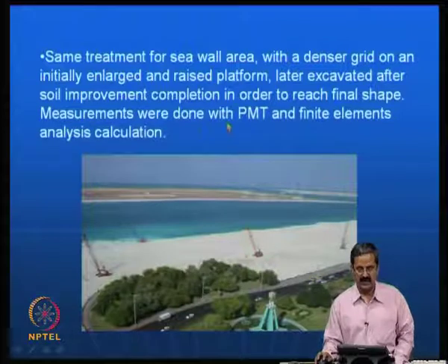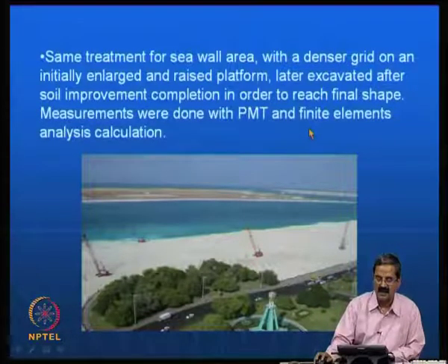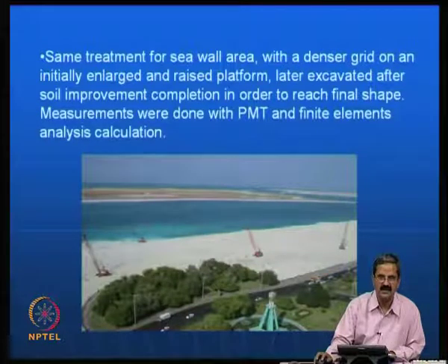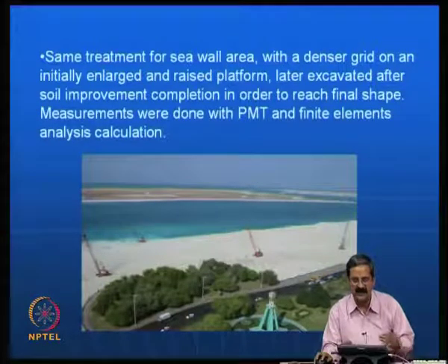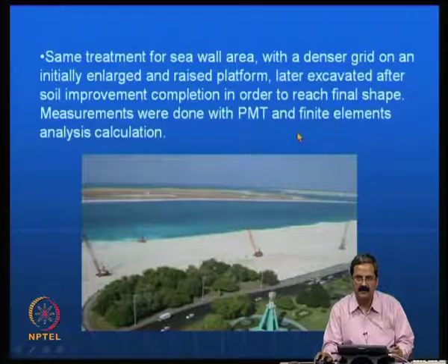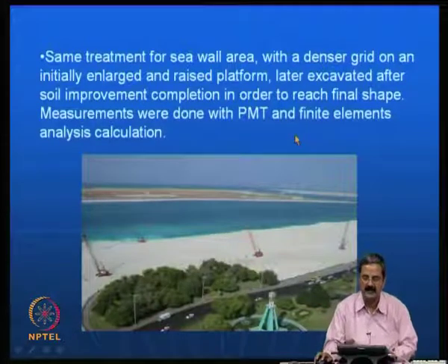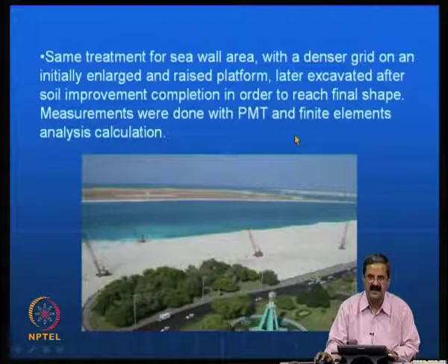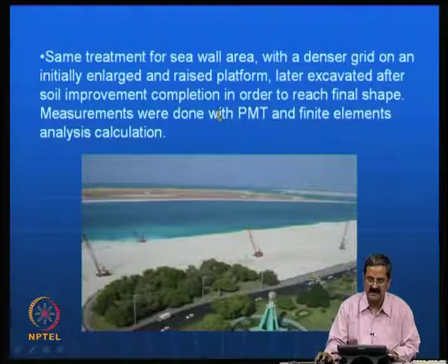Measurements were done with pressure meter tests and finite element calculations. In fact, one should verify some of these calculations and prove them, because you need parameters like Young's modulus, Poisson's ratio and other model parameters for finite elements, and one should use sophisticated testing. That is the reason pressure meter tests were used.